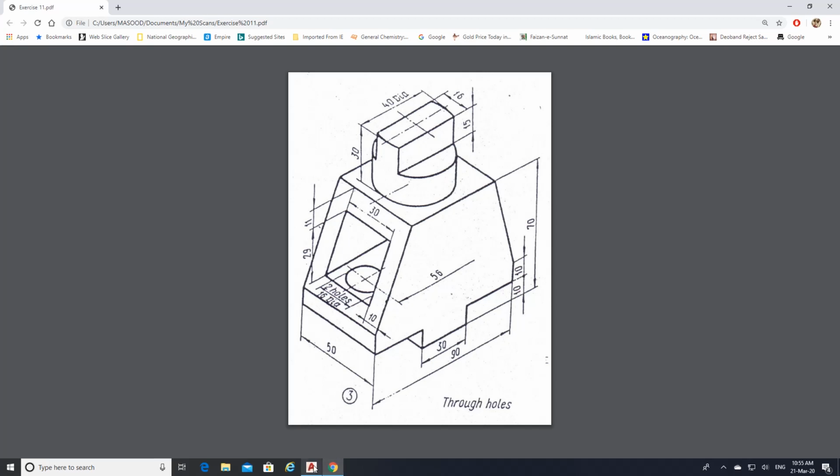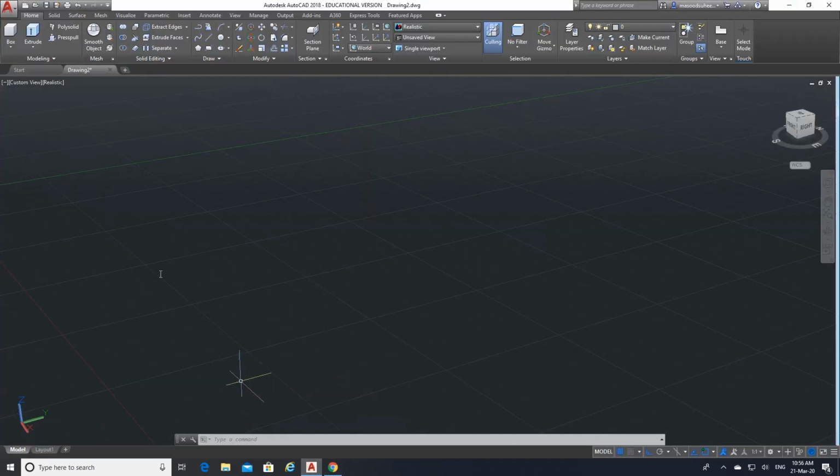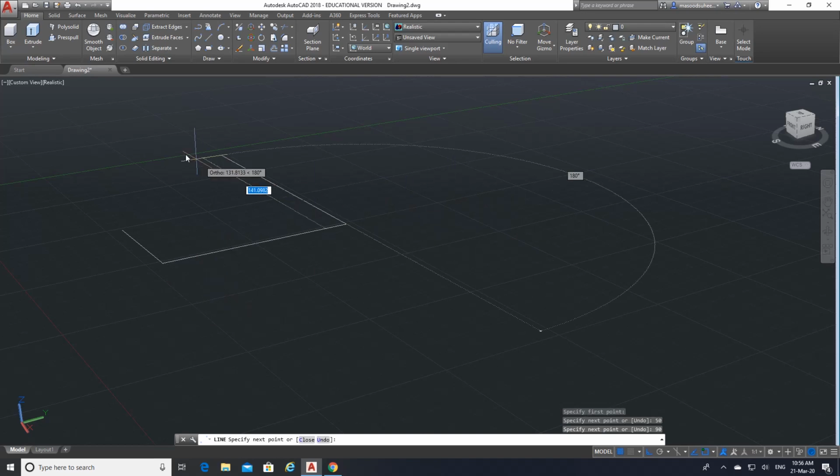Okay. So first let me open ACAD ISO 3D. I have already opened it over here. Let me go and then just click on straight line, click somewhere, make ortho on, come here, enter 50, then go in this direction, this is 90, then go back like this, 50, then come here 90, enter, enter. So I have already prepared one block over here.